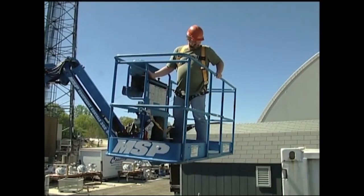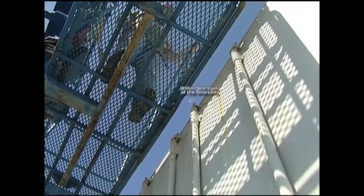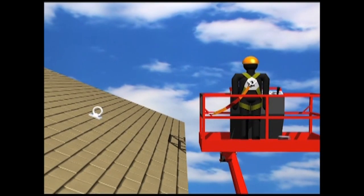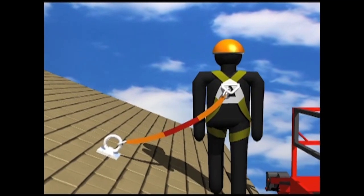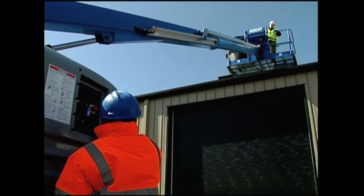There may be times when you need to get off a lift to get your work done. If you have to transfer from the lift to an adjacent structure, the platform must be within 1 foot of the structure. Use a 2-lanyard system, with one lanyard anchored to the platform and the other anchored to the structure. Once you've successfully moved to the structure, you can disconnect the lanyard from the platform. Finally, remember that unless there is an emergency situation, lower-level controls should not be operated while the lift is raised, unless the worker in the lift grants permission.